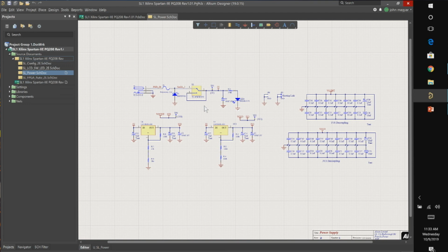Another thing to keep in mind is that the circuitry to do that isn't always these nice voltage regulators. You can get complex power electronics providing your source. So things like power transistors, and all of this is fairly straightforward to describe. So I'll show you an approach that's very general, and we start to think about our design in terms of, okay, what is my power source furthest back? Which things cascade through other components? So it's very common that you can see a hierarchy of voltage regulation. And I'll show you how to deal with that.